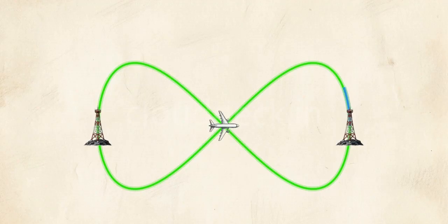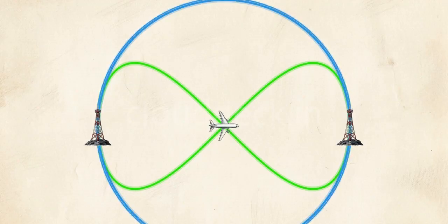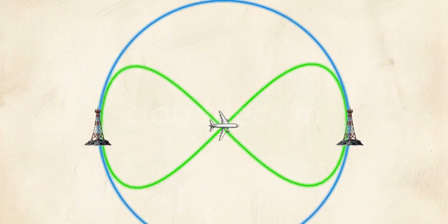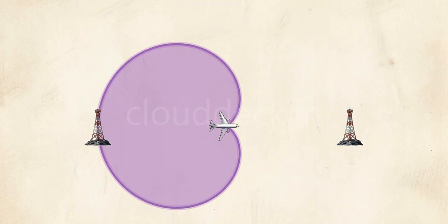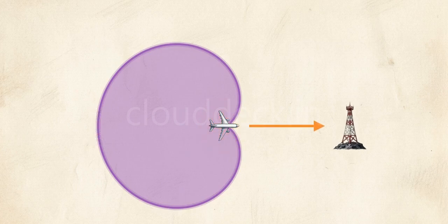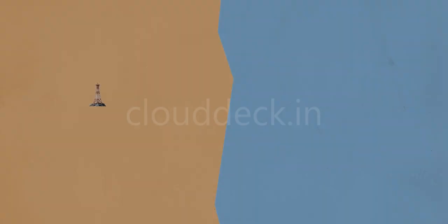By electrically combining that figure-8 loop pattern with a circular sense aerial, this diagram shows how the system generates a single heart-shaped cardioid wave. This cardioid contains exactly one sharp null point, allowing the instrument to definitively point at the station. But external radio waves are highly vulnerable to the environment.